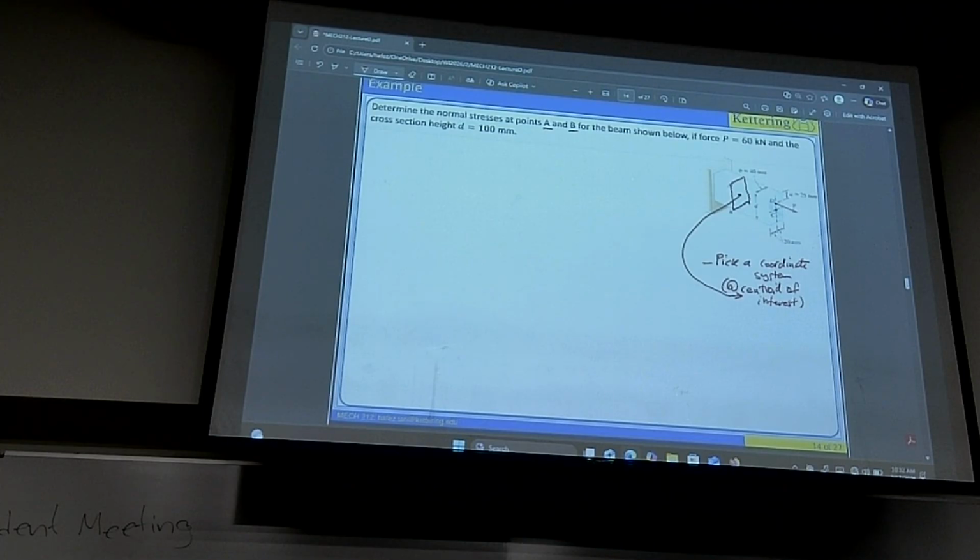All right, we pick a coordinate system. Three mutually perpendicular axes. Pick any names, but right-handed system, which means if you put the four fingers of your right hand along X and rotate them toward Y, the thumb of your right hand should point to Z. That's a right-handed system. In engineering, 99% we want that to be a right-handed system. Whatever labels you put there, stay with that.